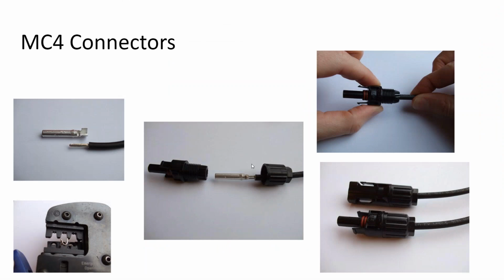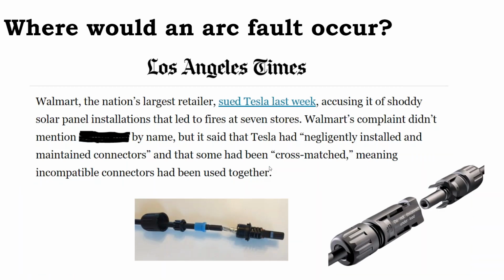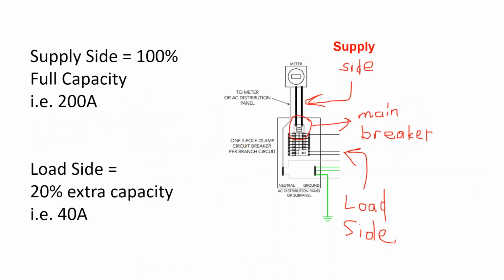Well, we're kind of out of time. If we had more time, I would talk about MC4 connectors, which are common failure points in the system when you're making up these home runs. So you have to do a very careful and intentional job when you're making these connectors, making sure the crimp is good, making sure the connectors are made up tight. Because these are common failure points in systems that don't have good connections and don't implement good cable management. It's stuff that an electrician does over his normal course of business, not something a do-it-yourselfer would have as much respect for.